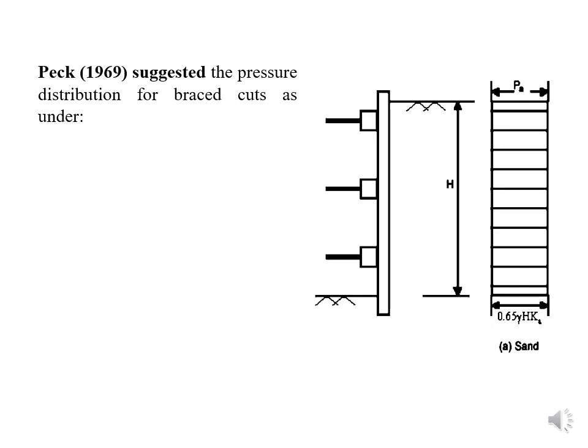You can see here H is the height of the excavated area, and the pressure distribution diagram. Peck has plotted the pressure distribution diagram for dry or moist sand.